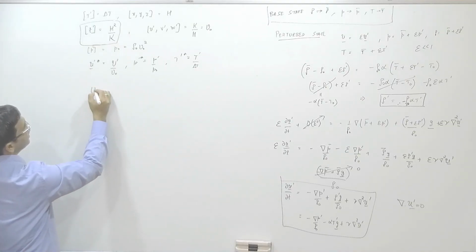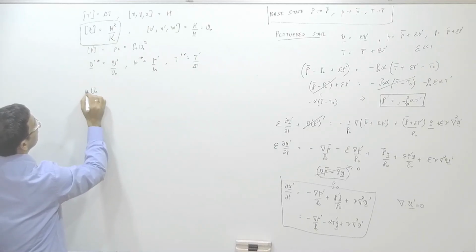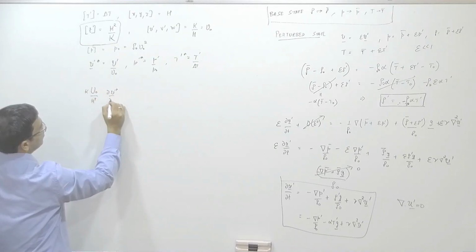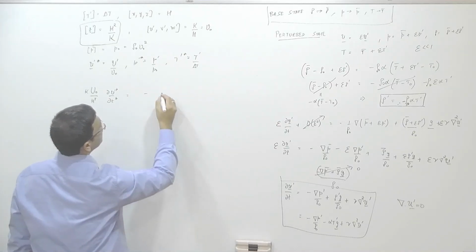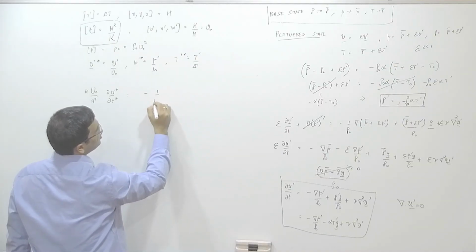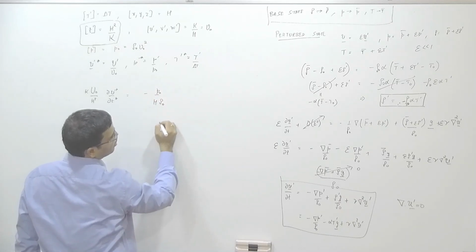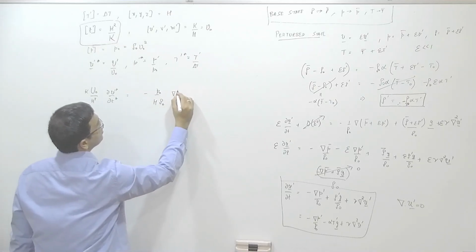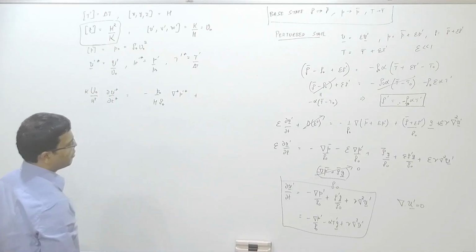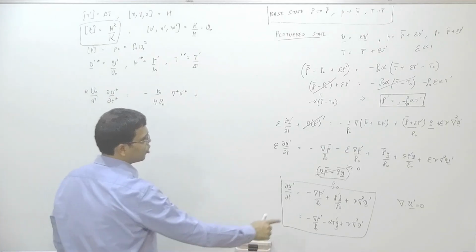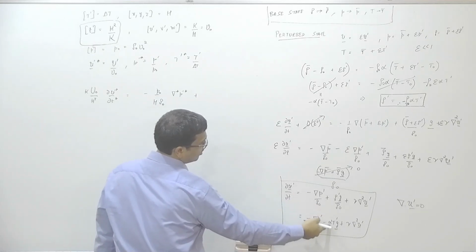So, now substituting them here, now time and length scales I am assuming that you guys are comfortable about here. So, you will simply get a u naught over this h square by k times del u prime star over del t star minus, what will you get here, 1 by h, and then a p prime has p naught, and then you have a rho naught, okay, grad star of p prime star plus a rho prime, but oh, instead of rho prime we are working with t prime, right?